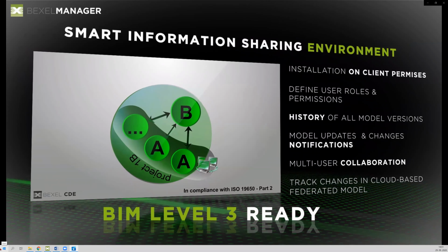If you create a regular selection set, it is by selecting elements directly in the viewport or within the custom breakdown. For example, if I click on this group, and also if I click on categories or families within the Building Explorer palette. And just to go back, why do I have here a custom breakdown? This custom breakdown is in the folder lesson 5 in the Exchange folder, and I have imported it as a BXF file.